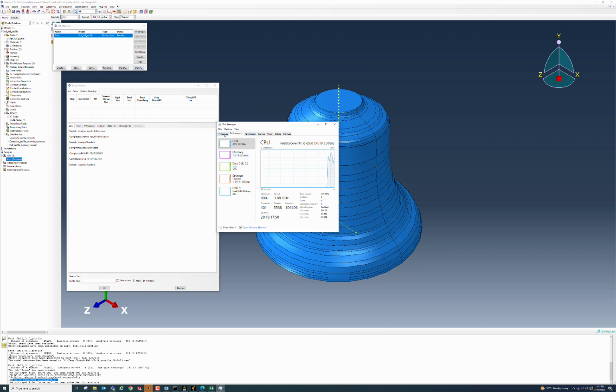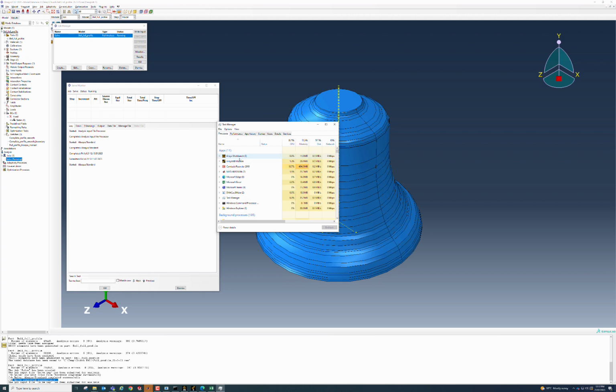If we've already completed a data check, we can then hit the continue button within the job manager. If we're starting from scratch, we hit submit, or if we hit submit after having done a data check, essentially the first thing that it does is recomplete the data check. So from the manager, data check first, wait for it to complete.